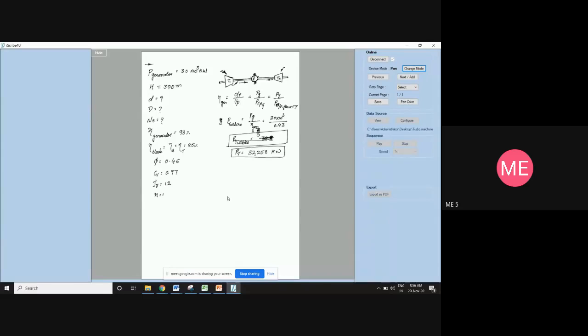For solving the derivation, the entire formula is based on only one turbine. So the power from one turbine is P turbine divided by 2, since there are two turbines. It will be equal to 16.125 into 10 to the power of 3 kilowatts. Correct? So this is the power output from one turbine. If you know how to take this power output from the given data, further procedure remains the same as we did in the previous problems.